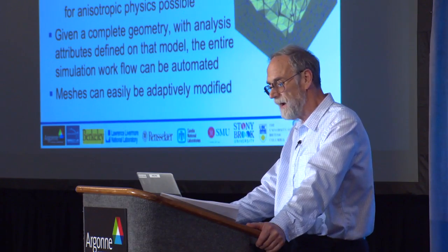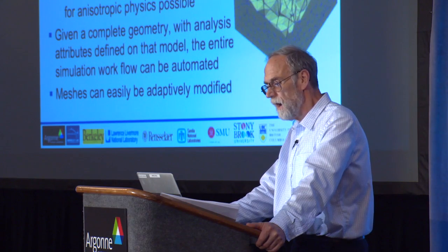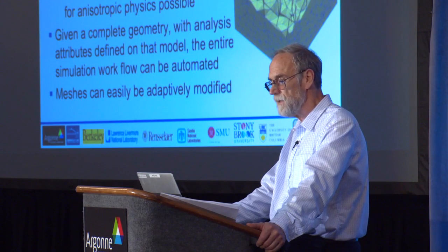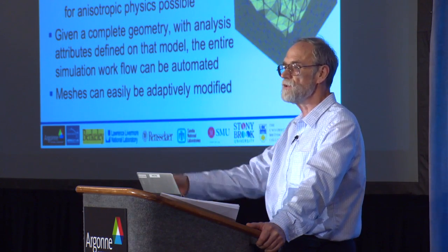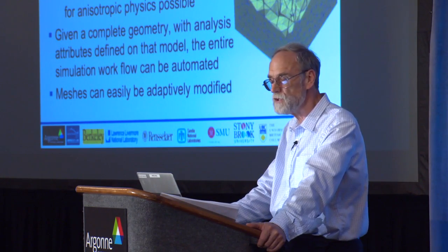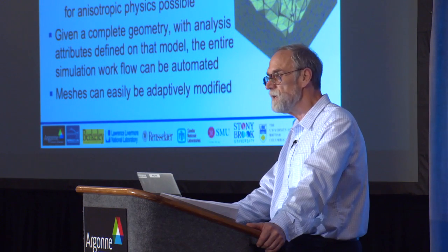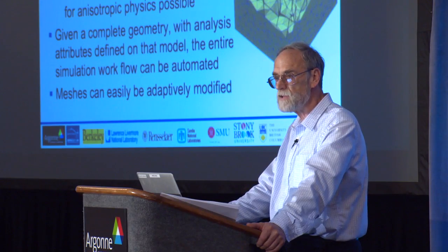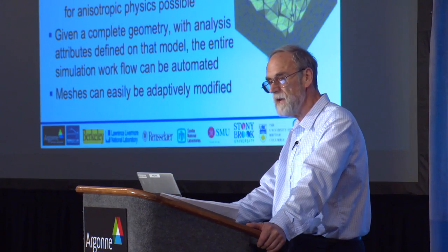They can provide highly effective solutions. They can easily fit exactly to the geometry, and you can track interfaces explicitly if you wish. They can deal with mesh anisotropy, so you can account for the anisotropy that you may have in physics behavior, such as boundary layers in fluids or whatever. And as I mentioned, they can be automated and easily adapted.